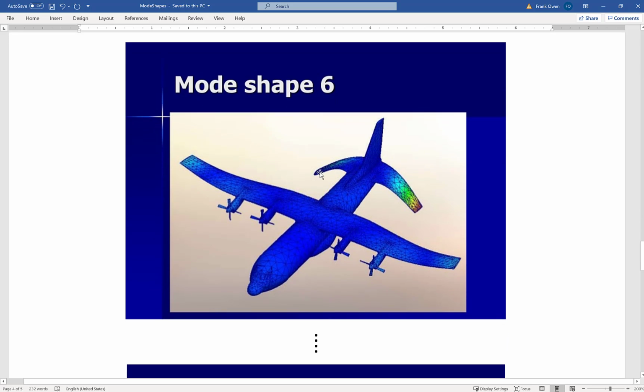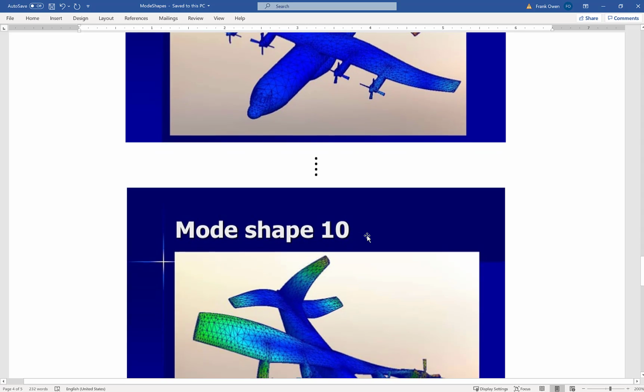Here you have your horizontal stabilizers flapping up and down. Your wing actually has multiple nodes and antinodes. But like I said, this will be a higher order mode. The frequencies will be higher and the amplitudes generally are less. But obviously they've analyzed this, so they're not saying, hey, this isn't important after mode 3, we can just stop here. They continue. And then you get a real crazy mode here.